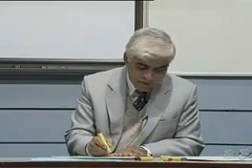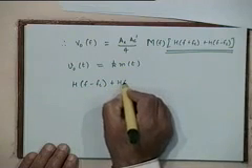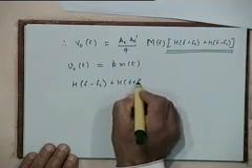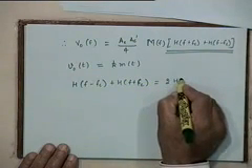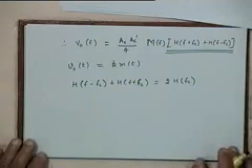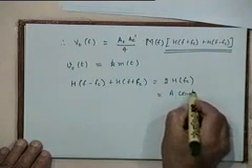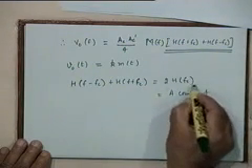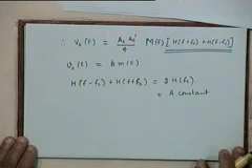That is the condition we are looking for, that H of f minus fc plus H of f plus fc should be a constant. Let's for convenience call it twice H(fc), because it doesn't matter what you call it. It should be basically a constant, and for convenience I'm just saying that let that constant be equal to twice the value at fc.